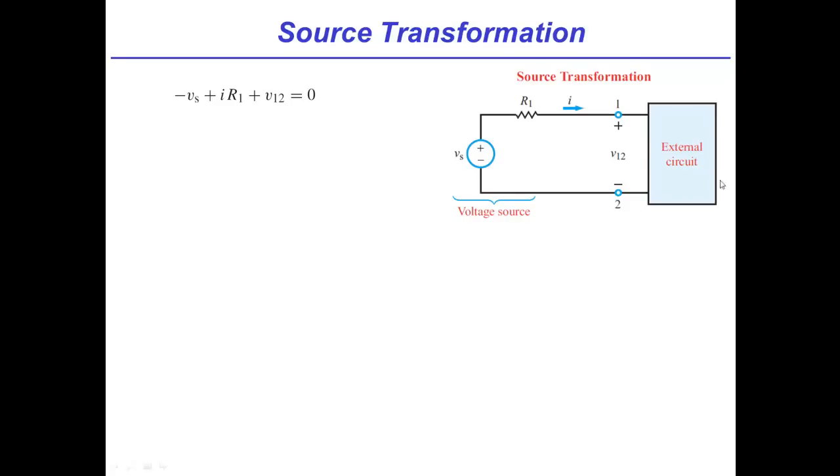That's exactly right. And this gets to, for example, your headlight example when you were talking about what this voltage is. But just, from this circuit, whatever the voltage drop may turn out to be, giving this a label of V12, we can write a KVL equation. And so starting from the bottom left and following what we taught you last time, we're going to write a KVL equation that is minus Vs, as we come up to here, plus I times R1, you can follow along on the left here, plus V12. And then it brings me back down to this node, and I'm done. And that equals 0, okay?